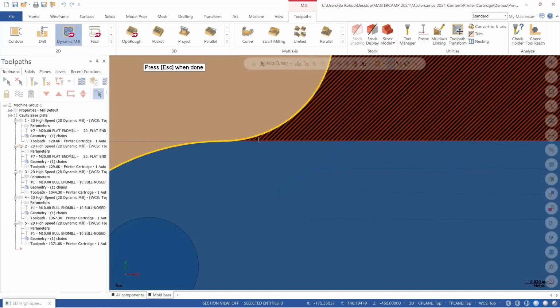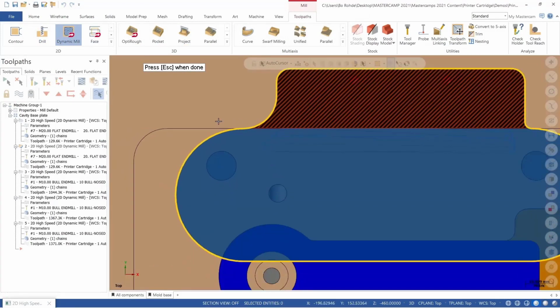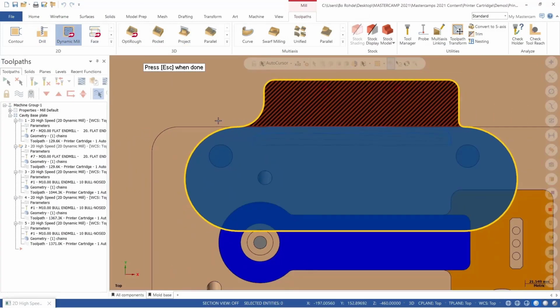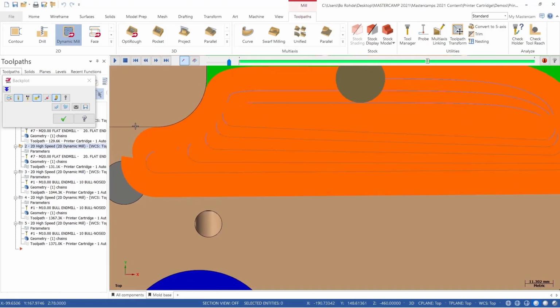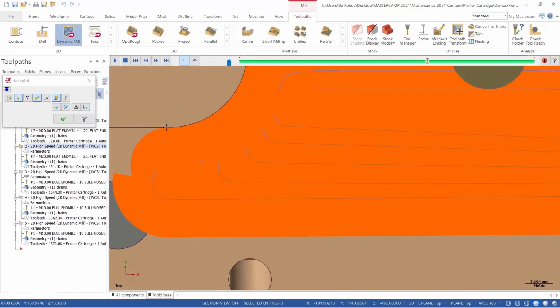it's giving the end mill more room to what I call roam outside of the cutting area. Now when our tool runs, notice how it's allowing the tool to come into the part a little bit sooner. And you can see now the tool is getting full engagement of all material coming out of the air region into the cut. I really like this one.